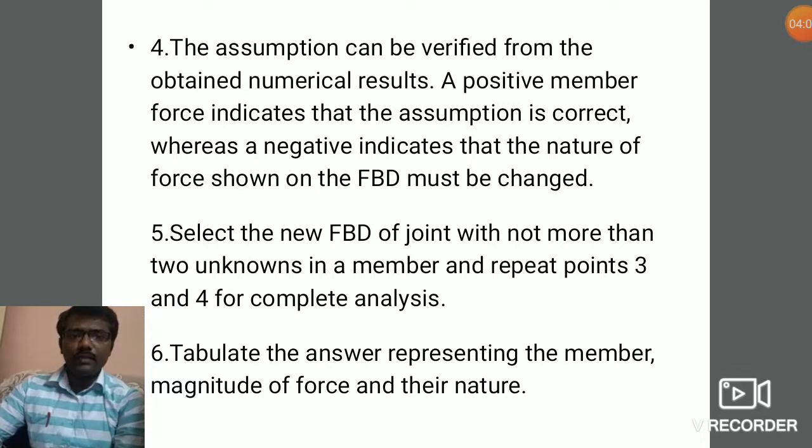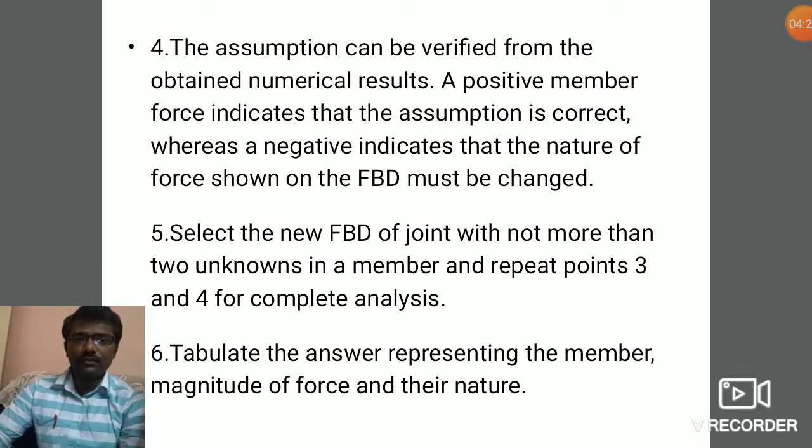And select a new free body diagram of the joint, where we again check the joint in such a way that only two member forces are unknown, and we repeat steps 3 and 4 to complete the analysis for finding the member forces. And finally, we tabulate the answers representing the member forces, the magnitude of the force in kilonewton, and the nature of the force.